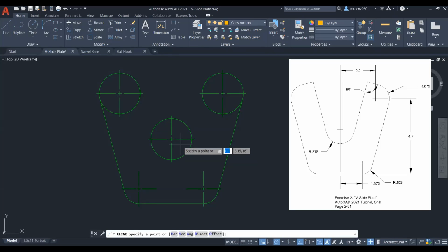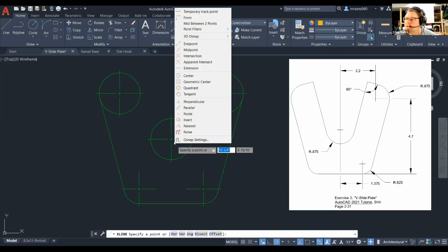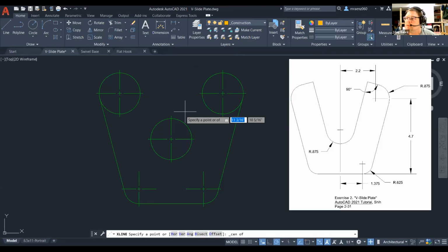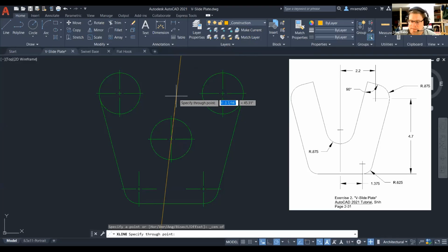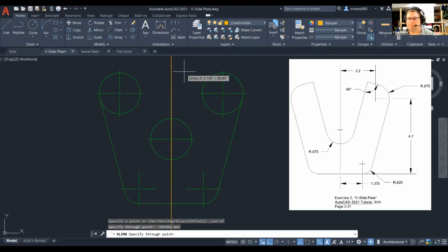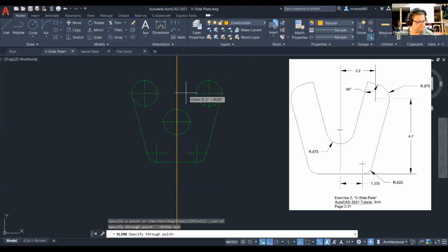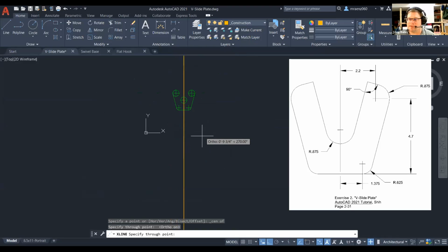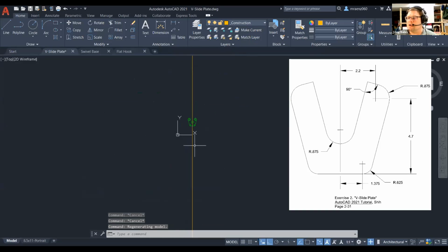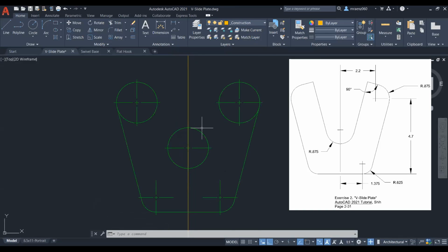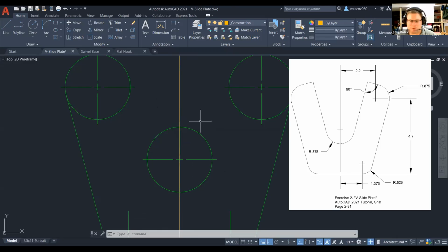And what I'm trying to do is recreate that central dimension line, and I'm going to use the center point of your circle. An X line, and then I'm going to go F8 to put it into ortho mode. I'm just going to shove it vertically, okay? Let me zoom out. Let's try to get to the end of that X line. Can't do it. An X line goes on forever. All right? So it's X for infinity. That's right. It's totally just for construction purposes only.